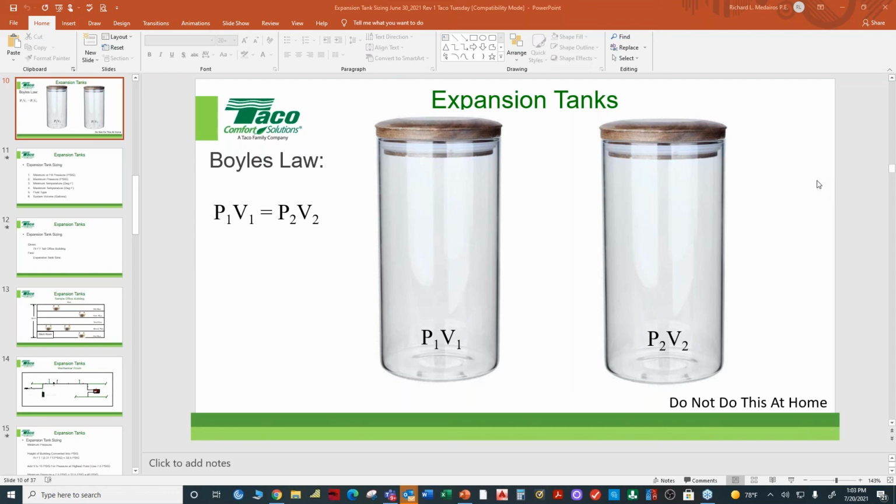Well, it becomes a judgment call, because if you specify and build a system with a boiler operating temperature of 150 degrees, hopefully you've also put in the necessary safety devices, both electronic and mechanical, so that if the boiler generates water temperature higher than its design, electronic devices that measure that temperature will shut the boiler off. If they fail, there are safety relief valves to relieve the pressure if the water temperature gets too high. So it's a judgment call, and there is no absolute answer to that question.